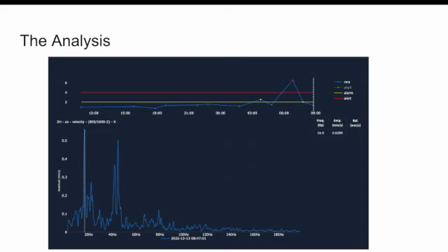So this is the data that we have. This is a vibration signal spectrum, and as you can see here, around 16 hertz is the RPM, the frequency that the machine runs at. This is the data that we have to analyze and classify whether it will break or not. Here you can see this red dot, which shows that probably something went wrong and the machine might not be working perfectly, and it can break soon if we don't do anything.